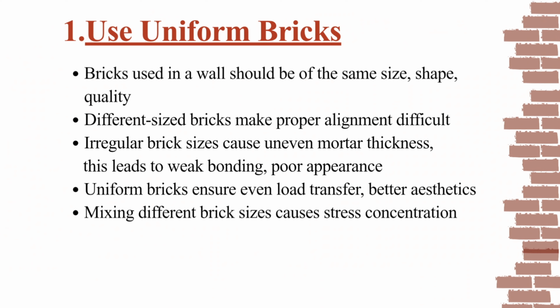In practice, mixing bricks of different sizes causes stress concentration at some points, which may lead to cracks, and that's why standardized bricks are always recommended for structural work. So it is most important to use uniform bricks while doing brick masonry work.